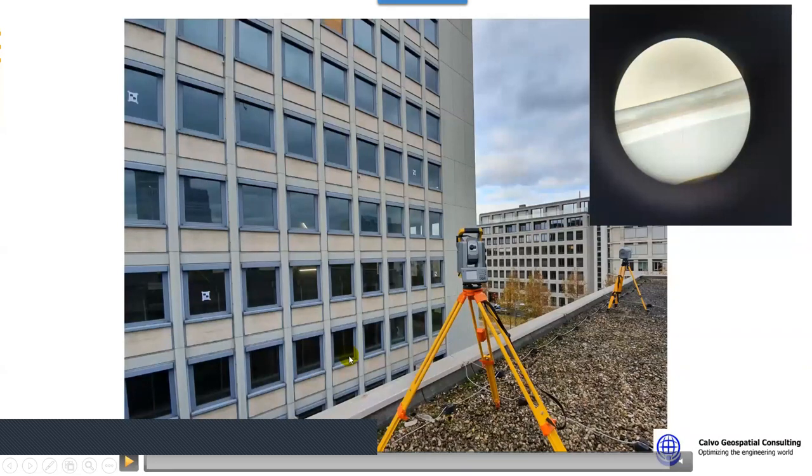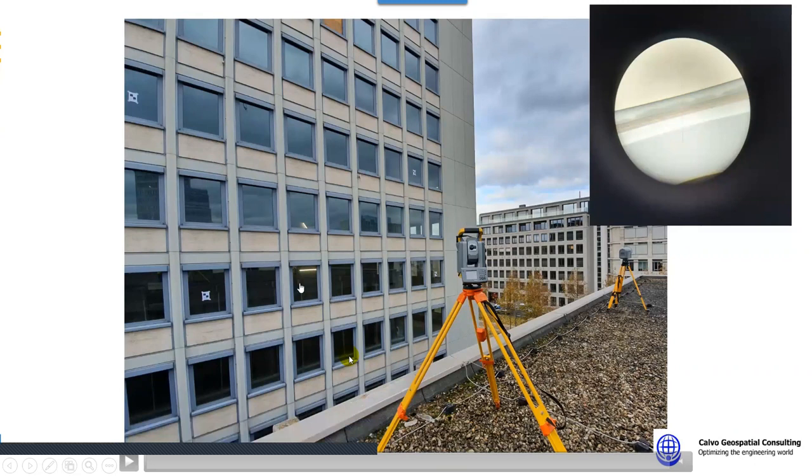So he does some measurement of all the targets mounted on the windows with the total stations. Then he uses the TX8 scanner to scan the building on the outside and then scan it on the inside. And you can see he's looking for very specific details in the point clouds or from the imagery that's collected by the machines to calculate these particular dimensions.